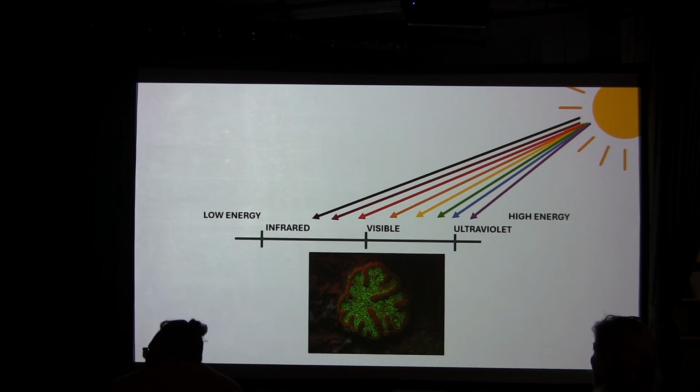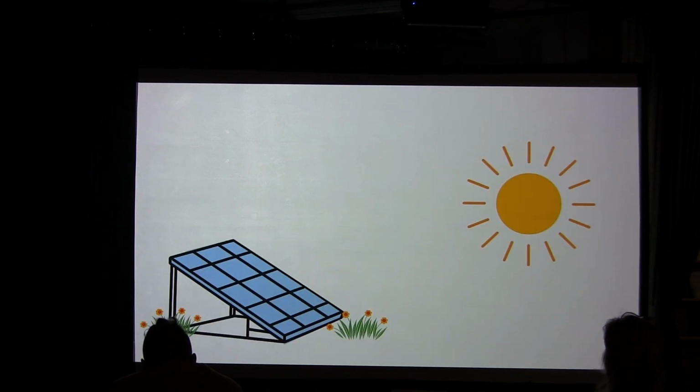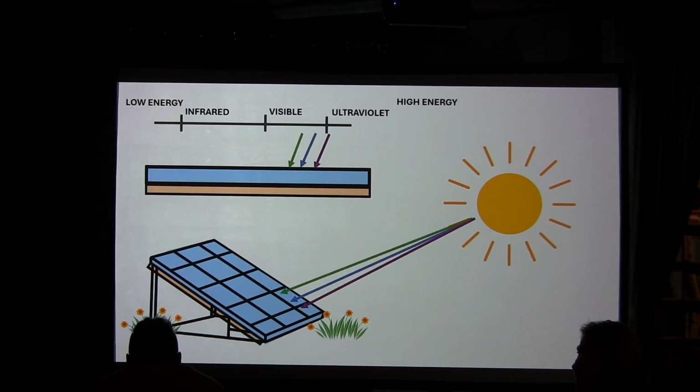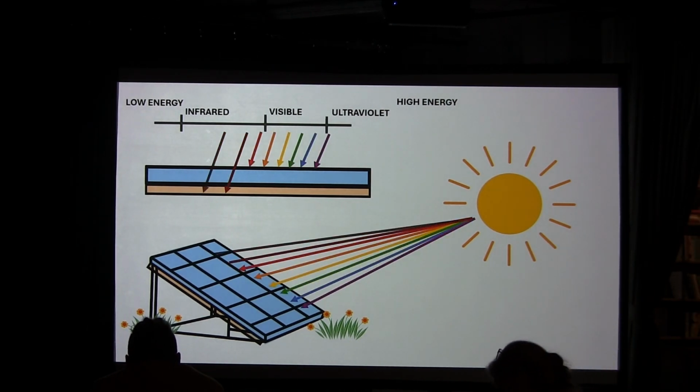To accomplish this, some scientists like myself have focused their efforts towards using a system of materials that can work together to do a process called upconversion, which is named for the phenomena of converting this light up in energy. The job of an upconversion system is to sit at the back of a solar panel and collect that low energy wasted light, but the magic is that it can actually convert the energy of that light into higher energy light that the solar panel can actually use to produce electricity.